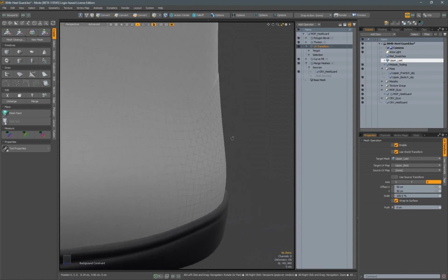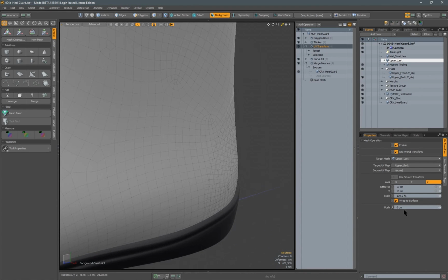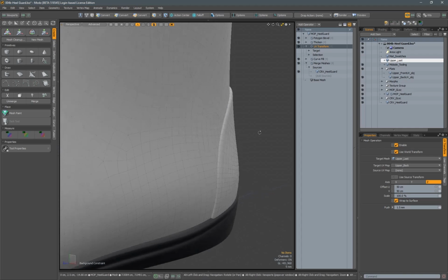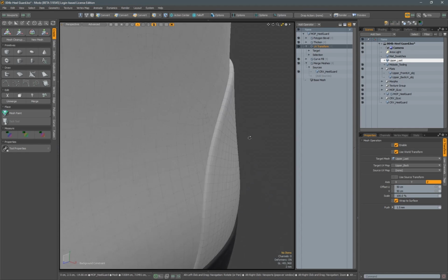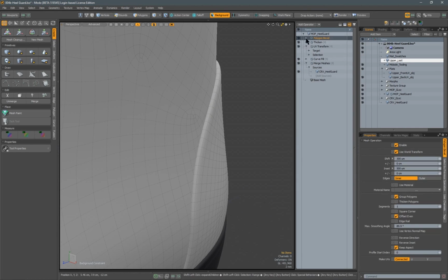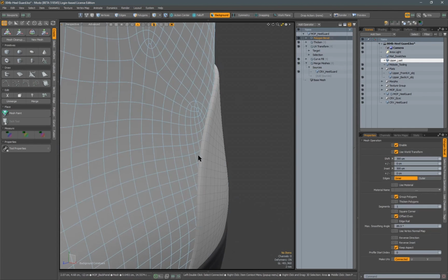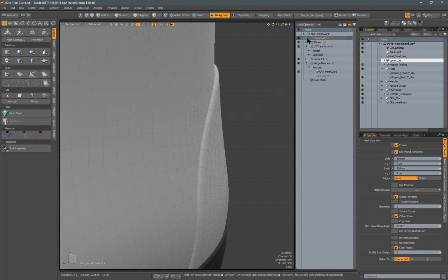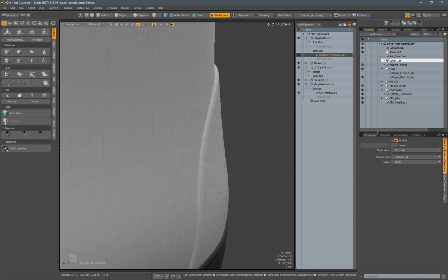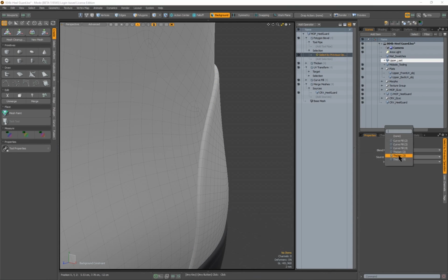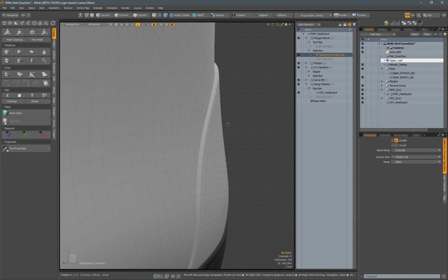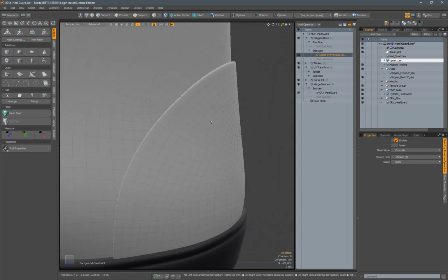Now for the back area here, what we do want to do is use the push function, and we'll say 0.15 centimeters, so that's 1.5 millimeters. And we also need to edit the poly bevel because it's not being beveled along that thickened area. So expand out that poly bevel, go to the select by previous, make sure it's selecting the thicken number 4, and there we go.